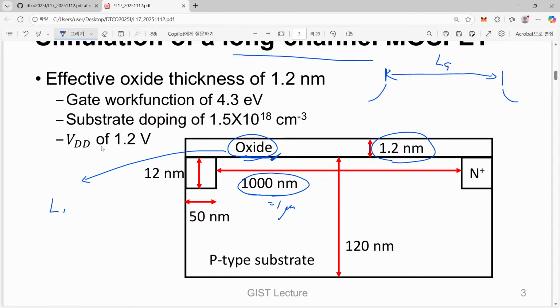Let's say that we have a minimum gate length which is acceptable to us, as a user of that device, meaning the device performance is more or less acceptable. Let's roughly say there exists a certain number L min. Then if we go to just twice or 3 times longer than this minimum length scale, we can quite rapidly approach the long channel properties. So it is quite easy.